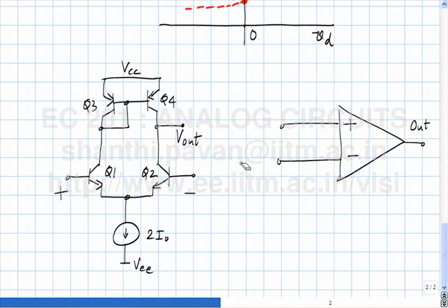Well, why are they different? No, we can always express any V. Please note that the gain is sufficiently large. Let's assume that GM times R is fairly large. In which case, if the negative feedback loop is working, then we expect the difference between the two terminals to be almost zero. So the finite difference between these two guys is not that much of an issue, is it?